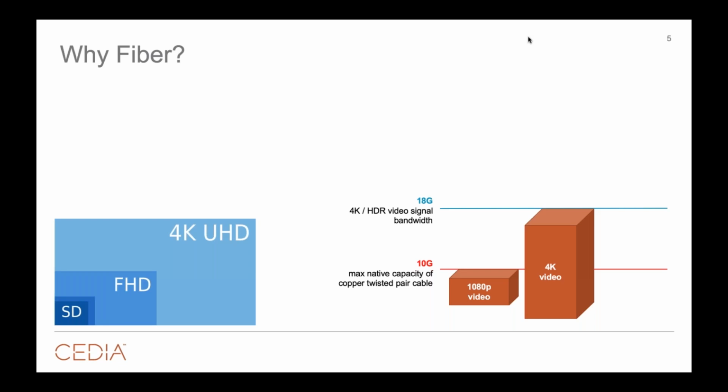And 4K is a very interesting thing, right? Because depending on what we're doing with that 4K signal, it could be 10 gig. Some manufacturers call it 4K 30, 10 gig 4K, right? HDMI 1.4 for 4K. There's a lot of ways to parse it and explain it. But the punchline is, 4K will go up to 10 gig, or if we're enabling HDR, if we're handling a 444 color space, we're going up to 18 gig.